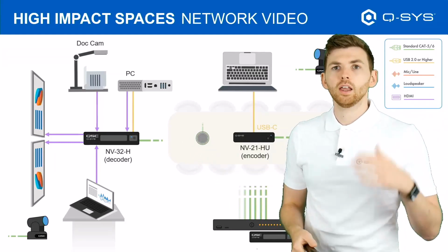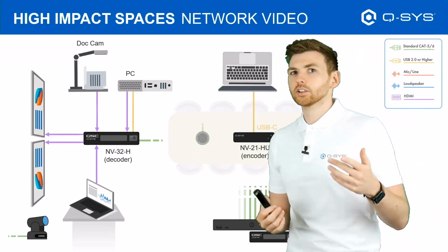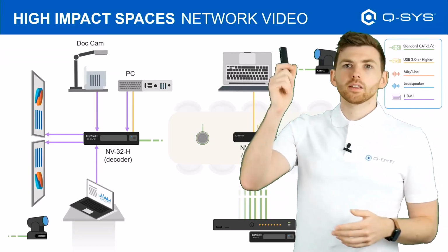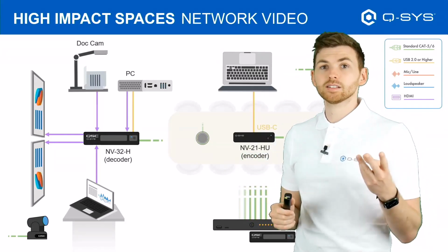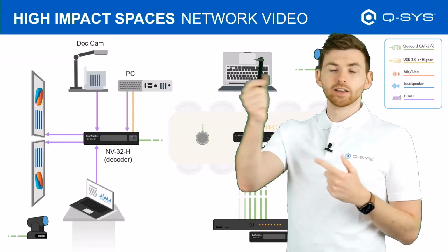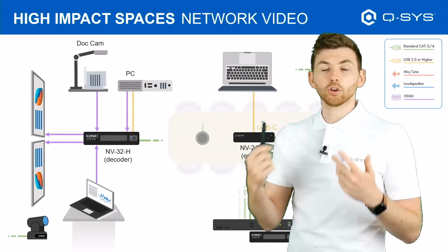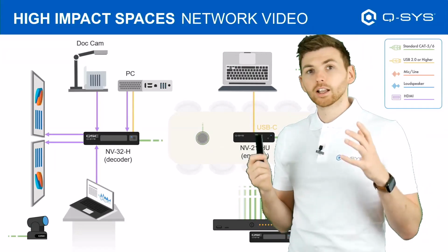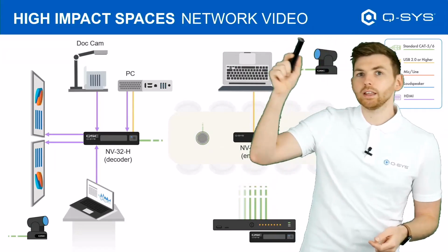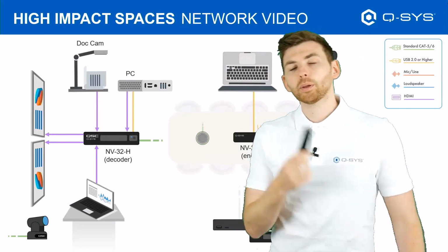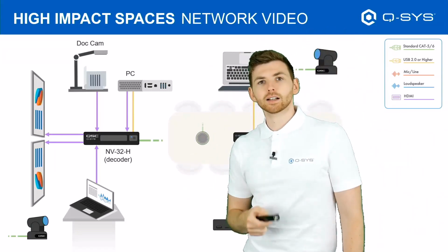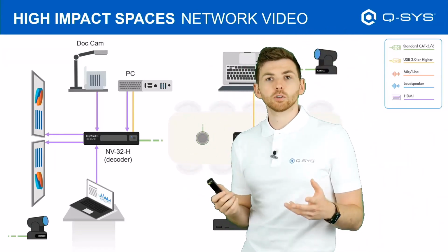However, it does get to a point where, if you've got 30 ceiling speakers and they're all network loudspeakers, that's 30 data connections. We're not daisy chaining the data on these, right? That's a lot of PoE budget as well. And that could be really valuable if you want to play different things to each speaker. That's actually a really great way of doing it. But if they're all just playing the exact same thing, then it's not super cost effective.